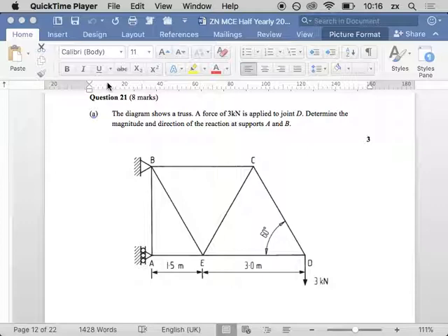Now I have minus reaction A. What distance away is that? Okay, the perpendicular distance from reaction A? It did require you to do some thought, right? Yeah, 2.6 is the answer. So what we have is an equilateral triangle that's 3, 3, and 3. If I cut that in half, now I have a triangle that is 1.5 and a 60-30 triangle.